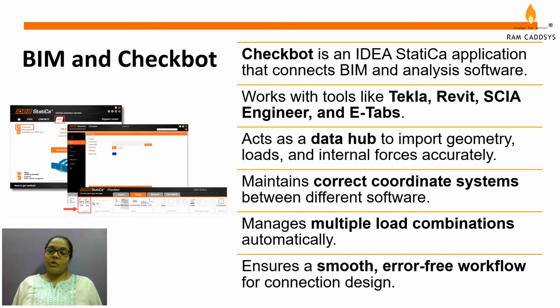Before I explain the Checkbot application enhancements introduced in version 25.1, let me briefly explain the Checkbot application in Statica. Through BIMLink, the Checkbot application is connected with different analysis software like Tekla, Revit, ETABS, and SkyEngineer, which can easily import the geometry, loads, and internal forces accurately. It also maintains the correct coordinate systems between the software, maintains the multiple load combinations automatically, and ensures a smooth and error-free workflow for the connection designs.